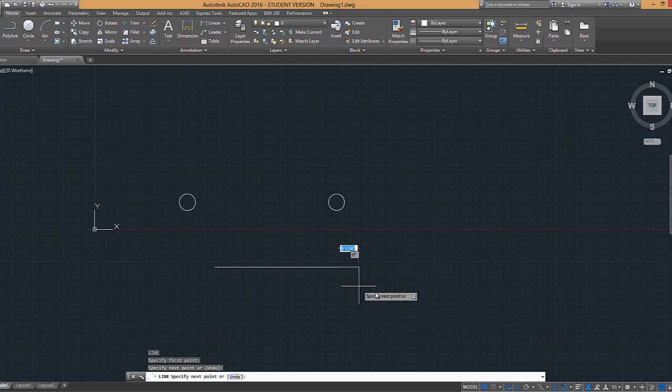So basically what that means is, let's introduce a line into here. For example, if I want one of my circles to connect to a line, I can type in CO to copy it to the end of my line. I'm going to mouse over it, and you'll see that this green indicator comes up, and if I just let go of my mouse for a second, it'll tell me that that's the center, and that's the object snap telling you what it is that it's snapping to.